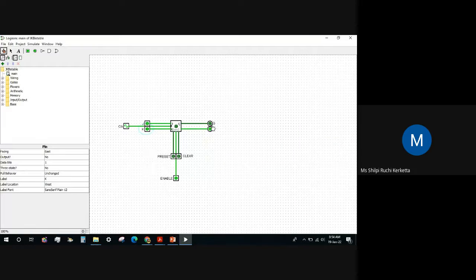So if we change the clock, we can see here we will get a 1 and here we will get a 0. So if we change this back to 1, we can say that q is becoming 1 and q bar is becoming 0. Okay, so this is the previous state, and again jk is 1 1. So again if we change back to 0, it is not working, so that is a memory state. Then again if we change back this clock, we will get an output of q bar. So again it will become inverse. We can see wherever we are giving a 1, it is like reversing because it is giving a q bar.